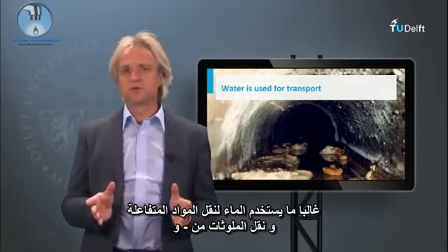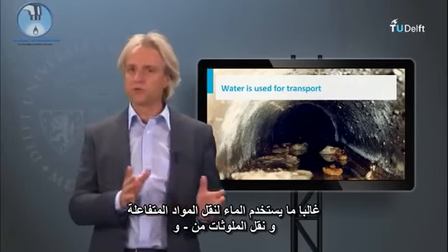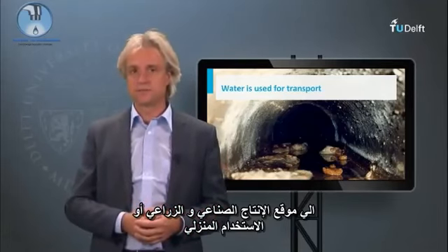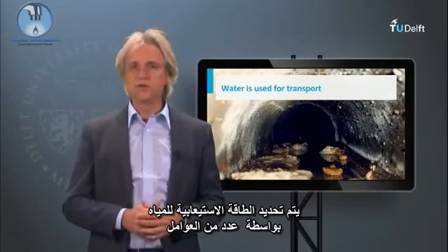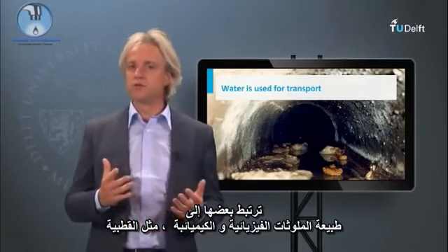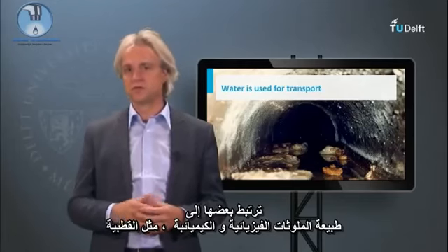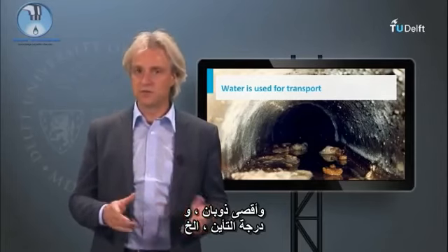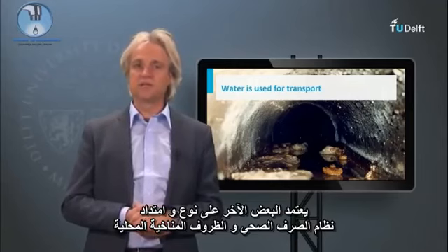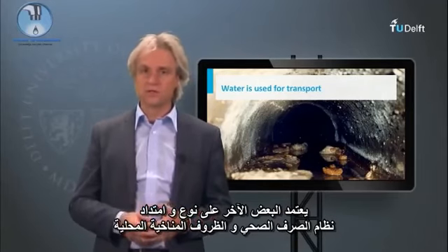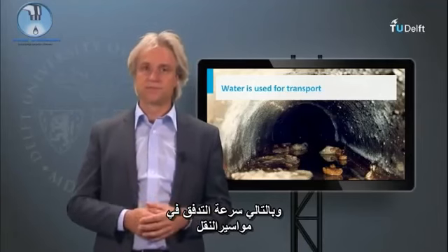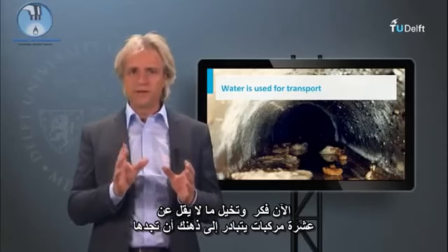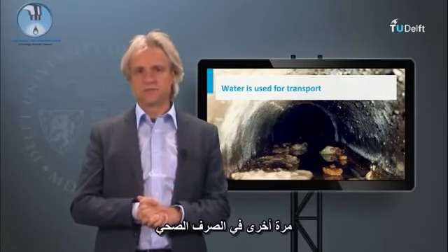Water is mostly used for transport of reactants to and transport of contaminants from the site of industrial and/or agricultural production or household appliances. The carrying capacity of water is determined by a number of factors. Some of them are related to the physical-chemical nature of the pollutant, such as the polarity of the compound, the maximum solubility, the degree of ionization, etc. Others depend on the type and extent of the sewage system, local weather conditions, and thus flow velocities in the conveyance pipes. Now think for yourself and imagine at least 10 compounds that come back to your mind that you certainly will find in the sewage.